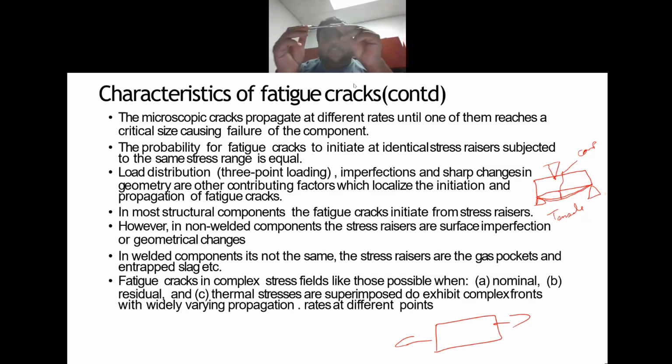So let's say this is the fatigue sample that I have. Okay, this is an aluminum. It's a metal matrix composite, so it has 20% silicon carbide in it, and it's a 2xxx series aluminum alloy. So it has copper in it and aluminum in it, and also it has 20% of silicon carbide to make it harder. So let's say this material.